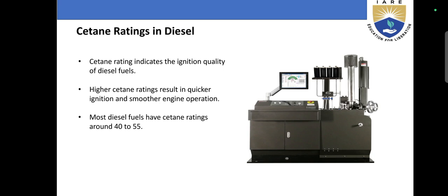Cetane ratings in diesel indicate the ignition and overall quality of diesel fuels. The rating will be higher for better fuels, and most diesel fuels have cetane ratings around 40 to 55.